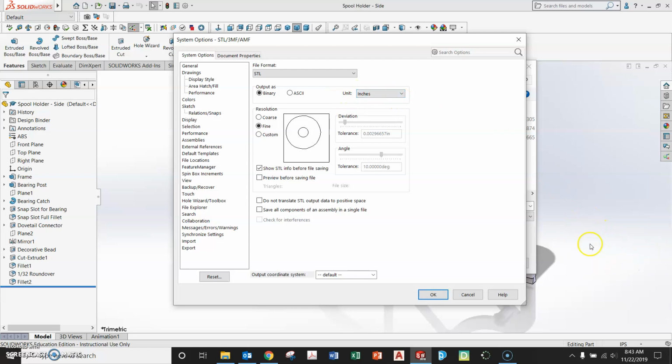It doesn't matter exactly what we created the part in. You can keep it the same as that, but then you're going to have to convert it if the software for the 3D printer is in millimeters. So in order to set this up for the Dimension printer, I'm going to export in inches, and I can leave this all alone. If it's an assembly file, you have a choice as to whether you want to print it as an assembly, or export all of its files individually. That would be that checkbox there. This is just a single part, so that's irrelevant to us.